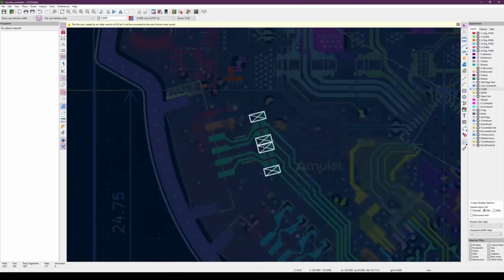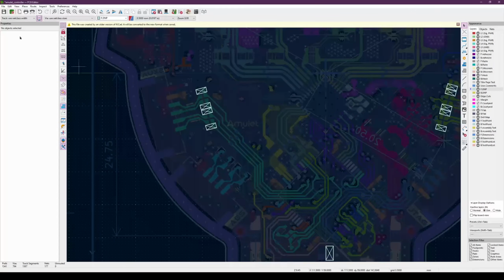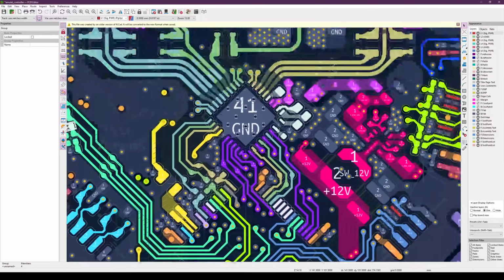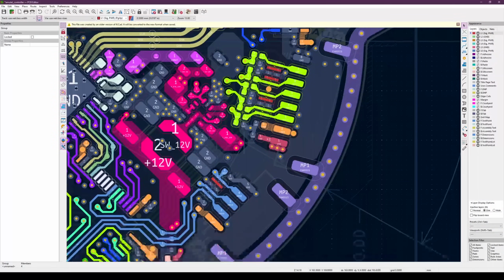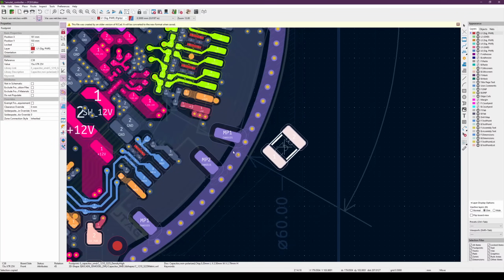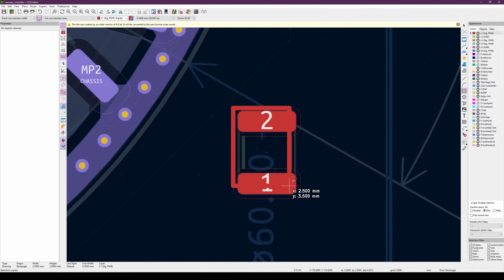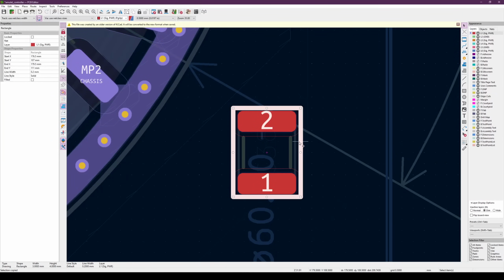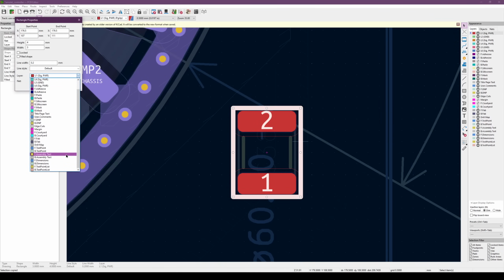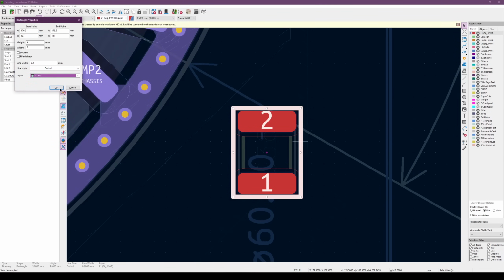And in order to make these, it is quite simple. So you simply get, for example, okay, let's just do it with one of these components. So for example, with this resistor here, what I simply do is I create a rectangle which matches the shape of that. Then I set it on the correct layer. In this case, it will be the front do not place.